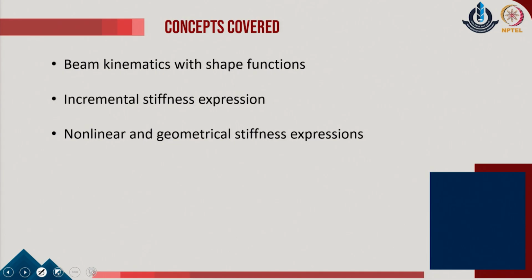So, this is the basic discussion which we will try to cover. We will identify the basic kinematics of the beam problems, which is possible for large deformation problems. Then we will also try to identify the incremental stiffness approach, similar to what we did in the trusses, and we will try to identify the nonlinear and the geometrical stiffness contributions of the given problem.